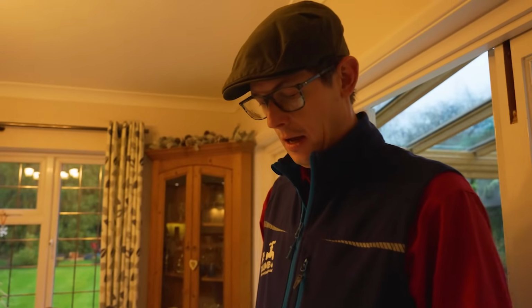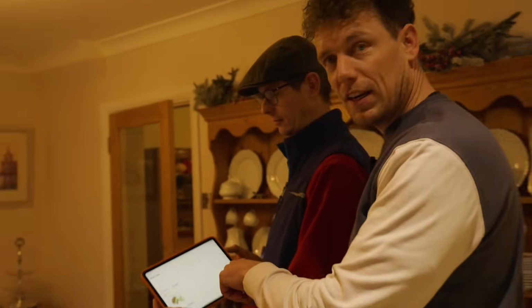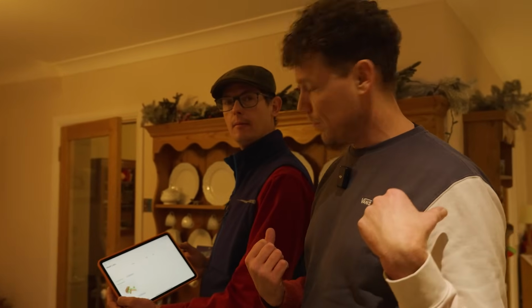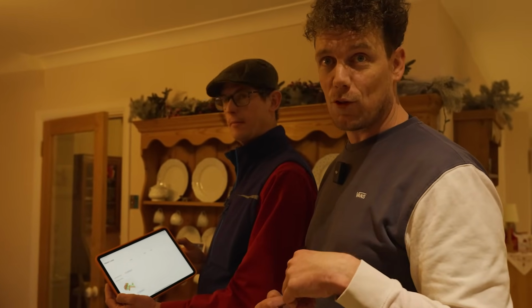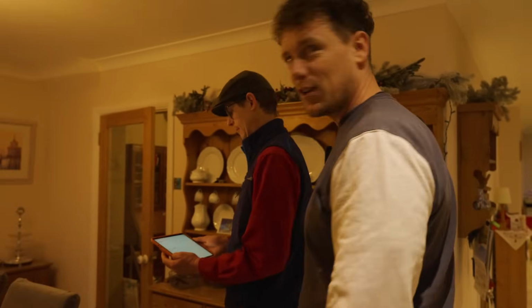How much time do you reckon that might save you then, Tom? I did one yesterday, smaller house than this, and it took me 3 hours. Is that without the app? Yeah, without the app. And I did one with the Heat Geek probably 2 days before, similar size house, and I'd scanned it in, I think it was 25, 30 minutes. So I was down the pub well early. So already from this one area, it's quite big, fair enough, but we've already got 2 kilowatts from one room, so, you know, it's going to be high.